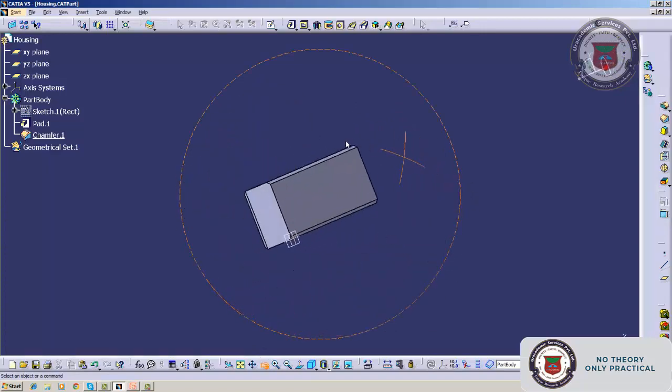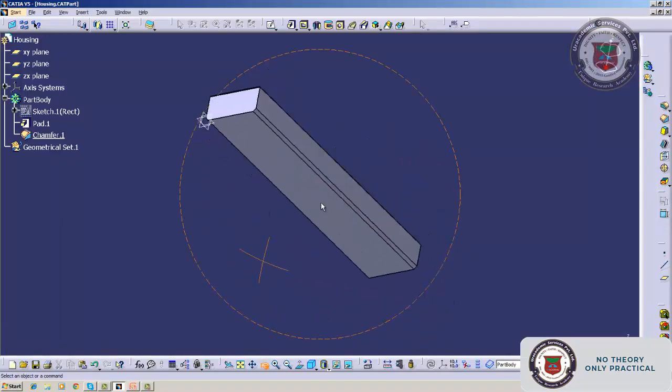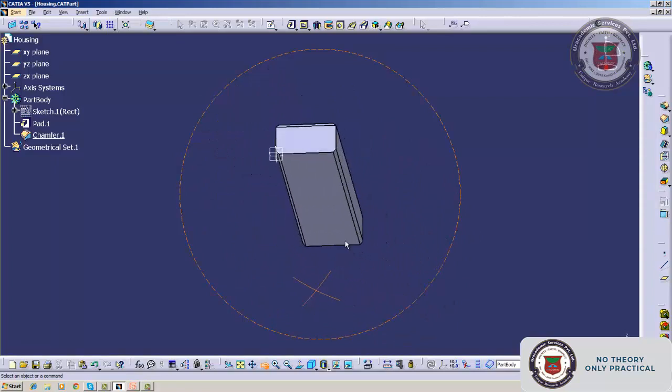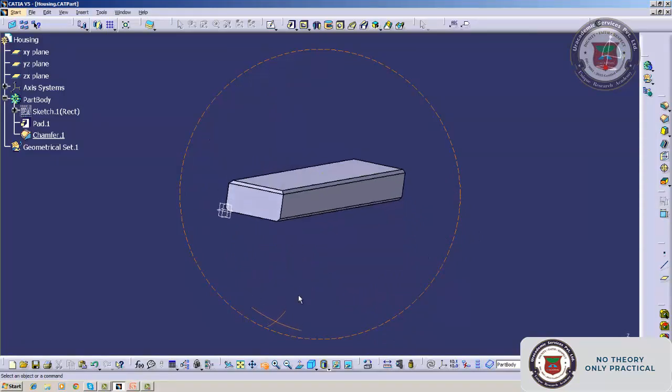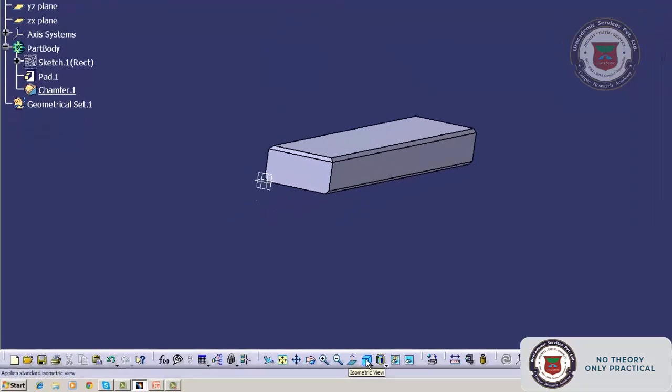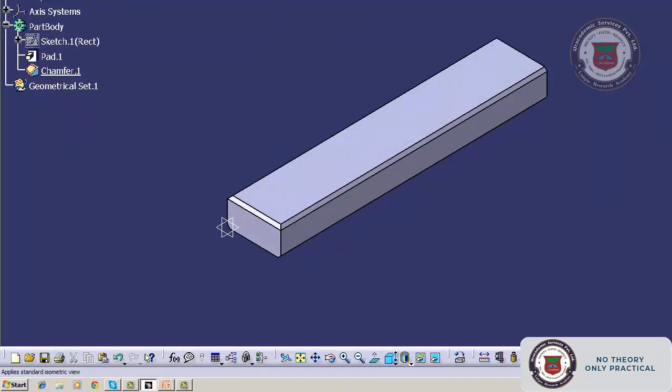So if you move it, you can move like this and you can see this. That is, I am holding the left button pressed and selected this rotate tool. This is called rotate tool. And then once you want to bring the normal position, isometric view position, click it here. In the isometric view, you hold it to the side and click left hand, you get various views.